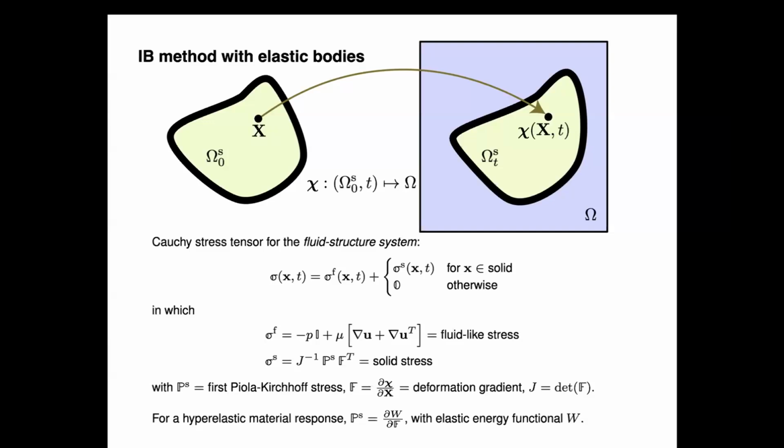What I'm going to be showing is mostly going to be using hyperelastic material models. So there's some strain energy functional of the deformation gradient tensor. The modeling work in terms of describing the structural response goes into describing the strain energy functional W. At the end of the day, we have a Lagrangian description of the stress. We like to formulate things using the so-called first Piola-Kirchhoff stress. So we're getting forces in the current configuration, but parameterized by coordinates in the reference configuration.